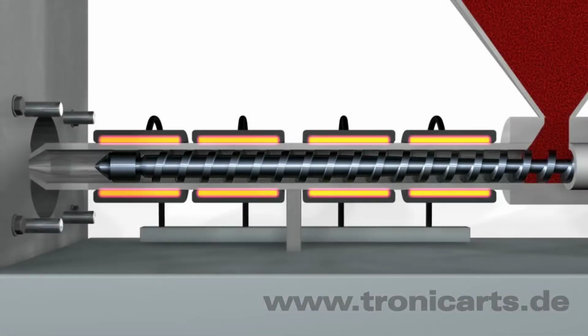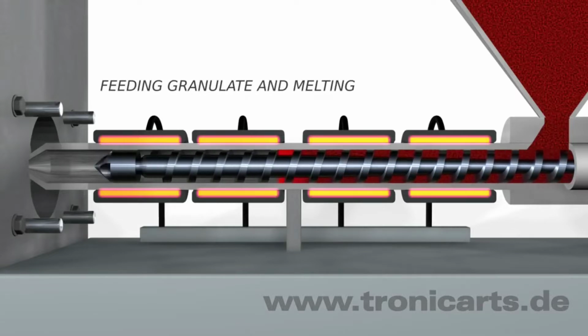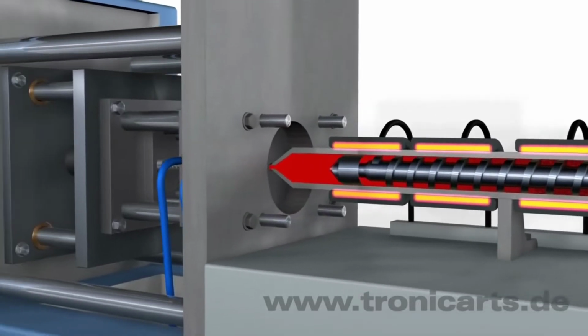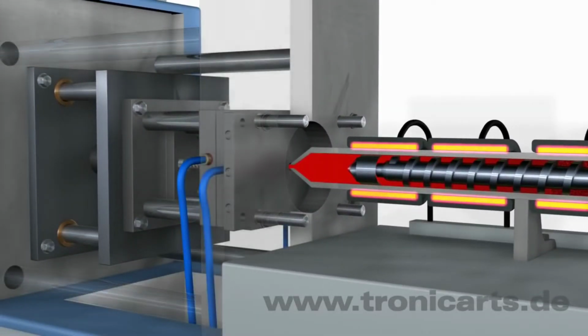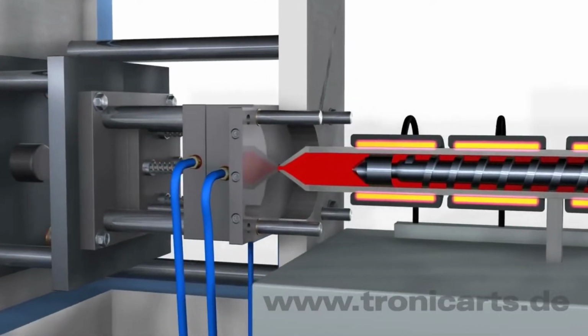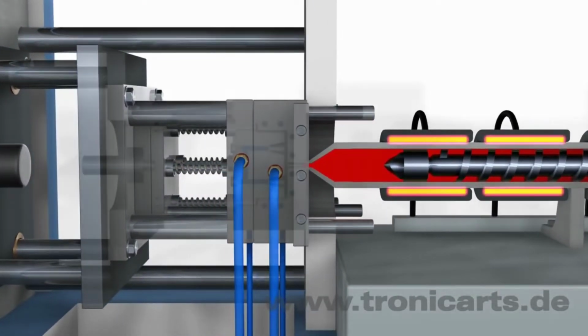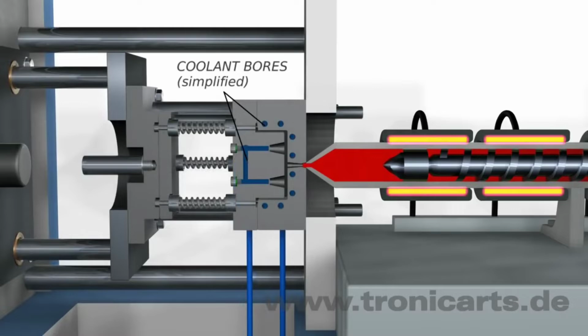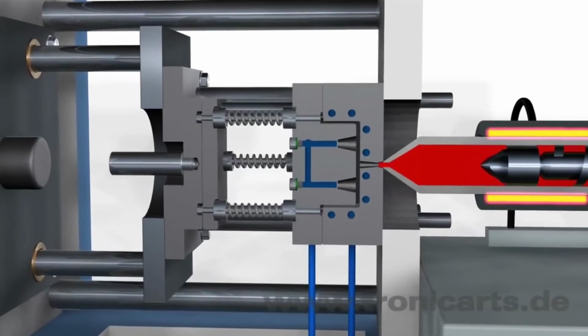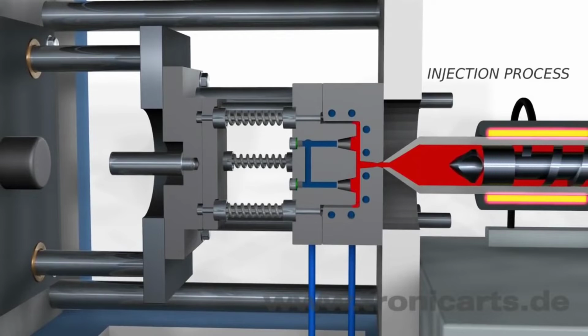The feed zone will carry the materials, and because of friction, heat will be generated that will melt the materials before they get to the metering zone. Okay, from there it is cooled by dosing, before it is pulled out, and the process is repeated again. The pressure in the system ensures that there is no deformity in the material being produced.